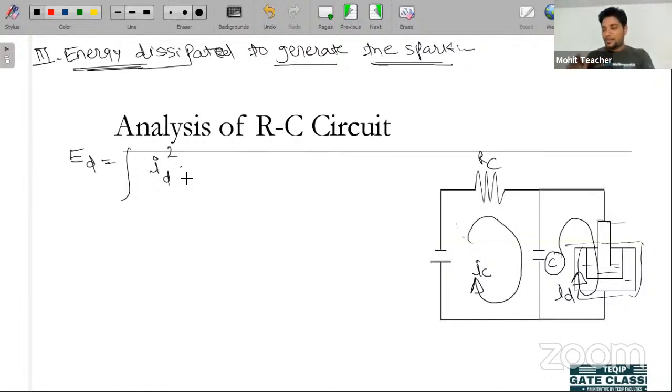So this will be Rm, okay, that is the machining resistance. So this will be Rm into dt, okay. Discharging means the machining one, this is Rm machining resistance, okay. Now we are using this current, so initially this complete energy is dissipated during the discharging only. Initially when there is no energy dissipated, and at the end the discharging time is there, at that time complete energy is dissipated, so we are calculating that one.